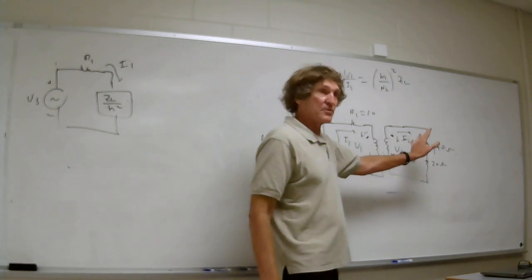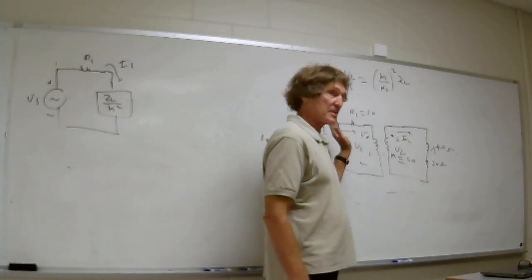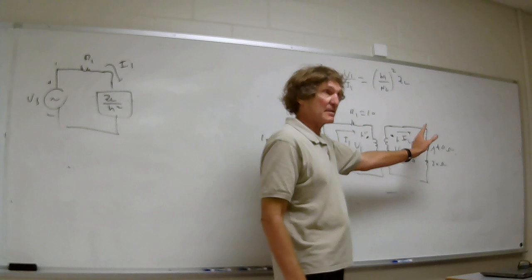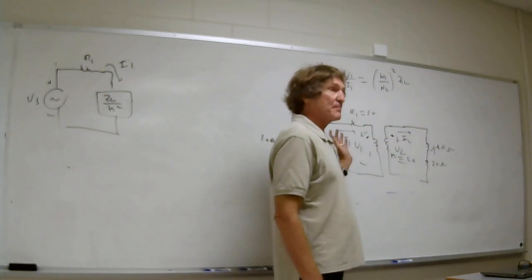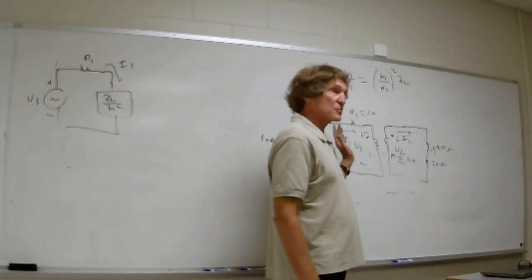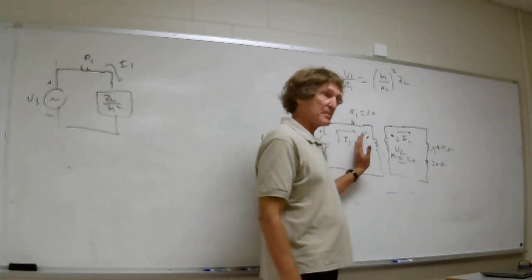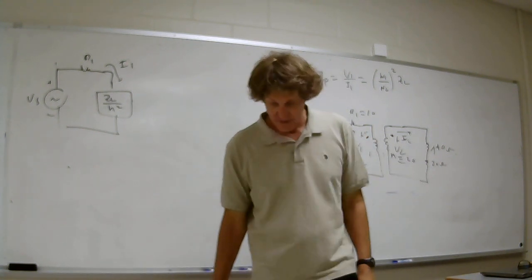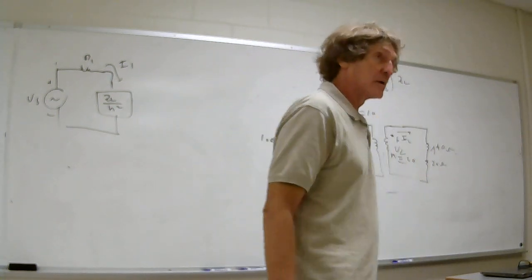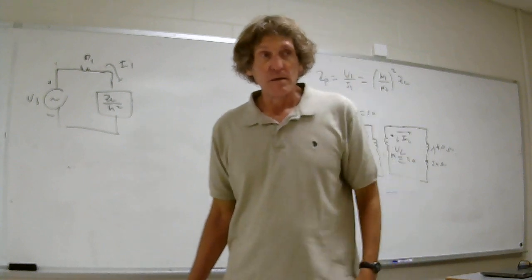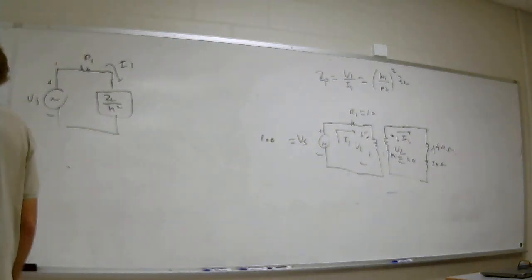So there's 20 turns on the secondary for 1 turn on the primary. The voltage is going to be 20 times as much, and the current is going to be 1/20th. The reflected impedance is going to be 1 over N squared, so this side has a lower reflected impedance than that side. That 20 is a ratio, 20 to 1. Okay, I gotcha. I wrote Z1 and Z2, and then I assigned Z2 as primary when it's supposed to be the load. I just did it backwards.